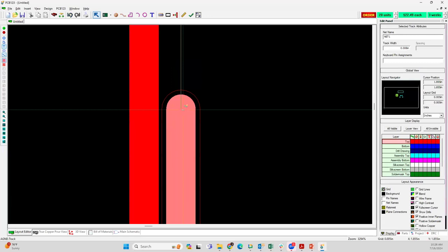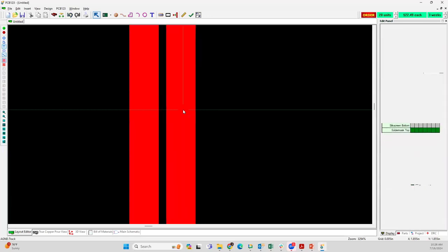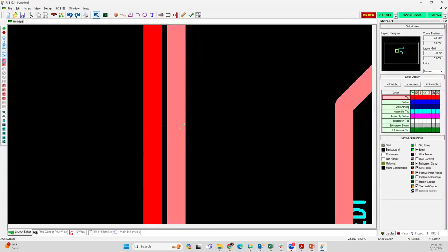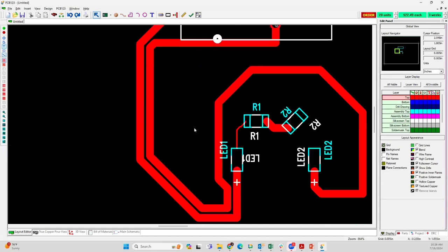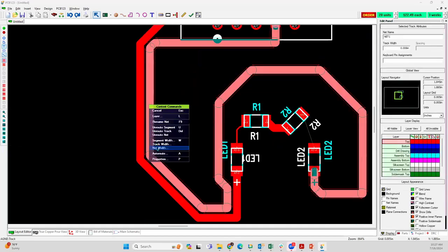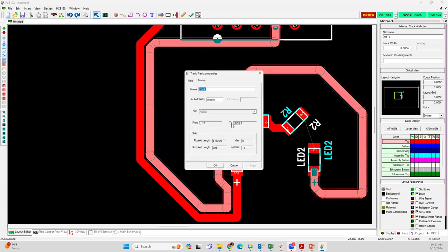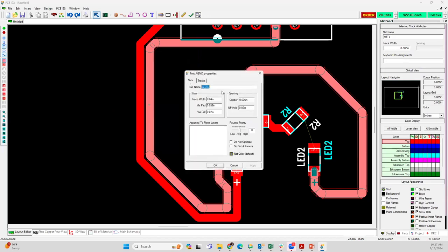And these wires are, I don't know what the default setup was of the spacing on these wires, but it's easy to find. Properties, default spacing on nets. Trace width is 40 thousandths. Copper to copper is 6 thousandths. So it won't let you route any closer than 6 thousandths to the next trace, otherwise it throws an error.